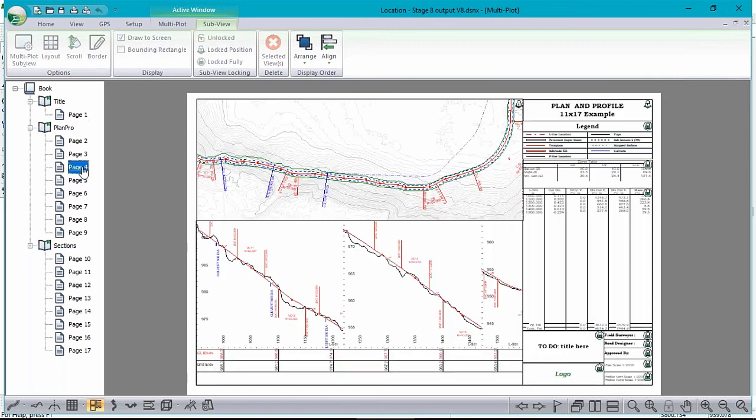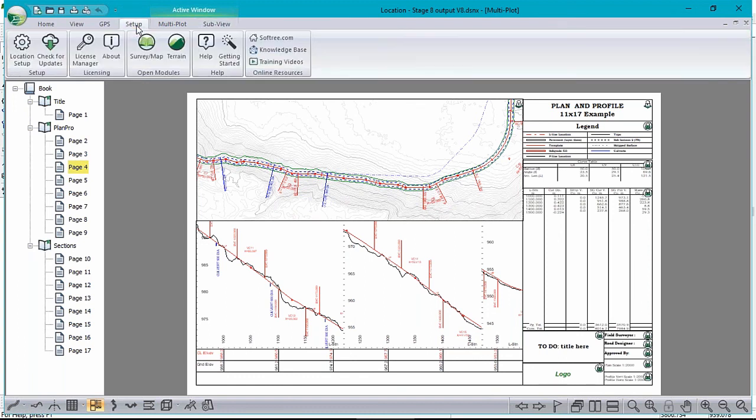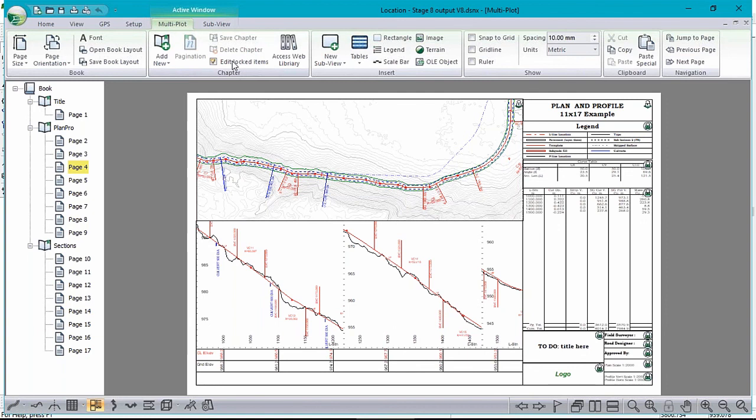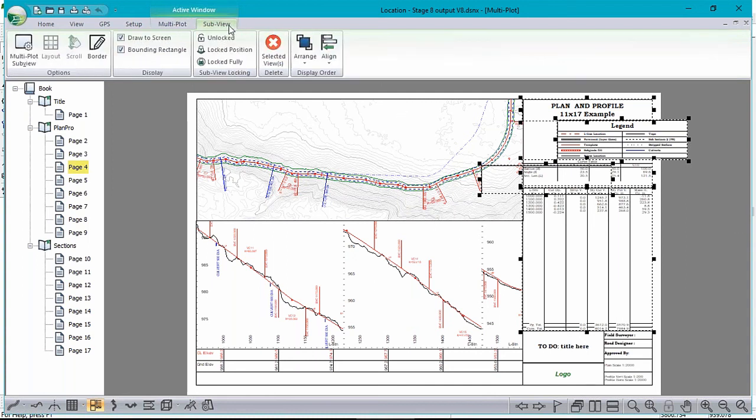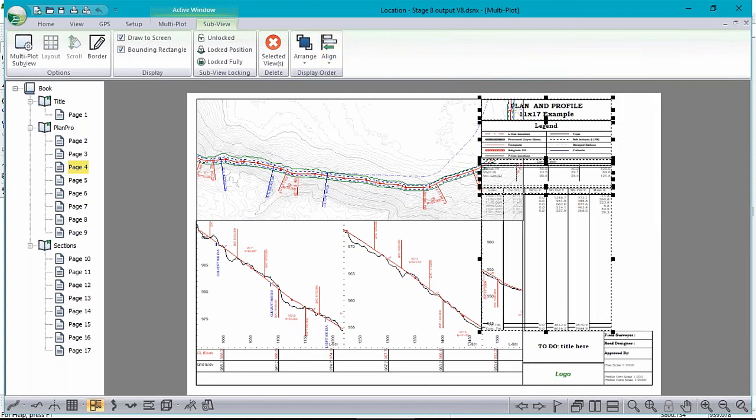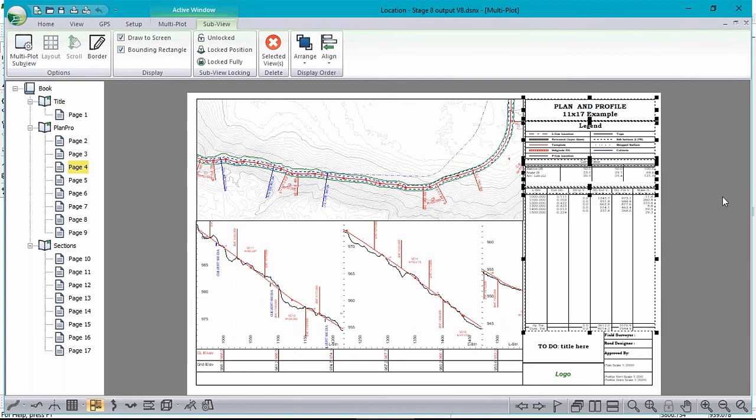You can also select more than one thing and align them side by side. So let's just go to here and say these things get out of align. So let's unlock them all. I got a bunch of locks turned on here. So I'm going to unlock them all so I can edit them and then start moving them around. That one will move over there. This one will move over here. And now if I select all those, we changed selection, by the way. It's no longer just crossing. You have to actually wrap right around the window to select it. And I missed this one, so shift click should, oops, I guess it's control click. Anyway, if I select those items, just those 4, there might be another one in the background there, I'm not sure. And go into the align thing, and I can say right, and they all line up to the right-hand edge. Looks like for the top one, but of course now I can just move them together, and yeah, they're all aligned.